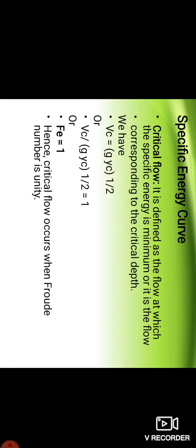That covers the specific energy curve and the critical flow. Critical flow is the flow at which the Froude number is equal to 1, that means the flow at which the specific energy is minimum.